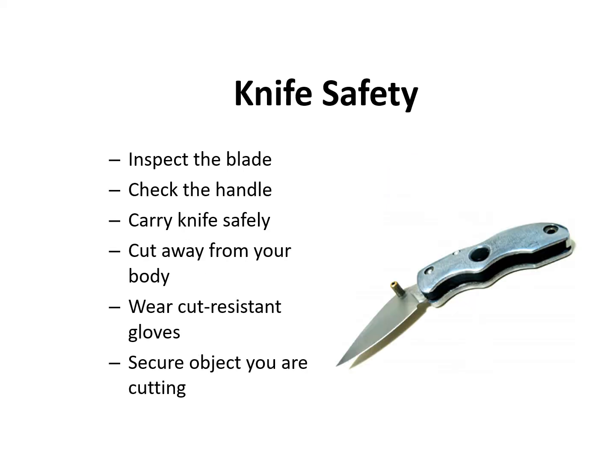When using a knife, inspect the blade to make sure it is sharp. Check the handle to make sure it is firmly attached to the blade and there are no signs of damage. Carry the knife safely by either closing the knife or inserting the knife into its sheath. If necessary, carry an open knife down by your side with the blade pointed down and away from your body.